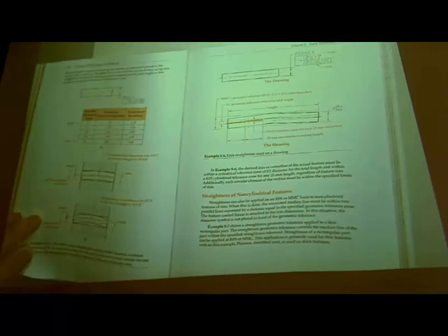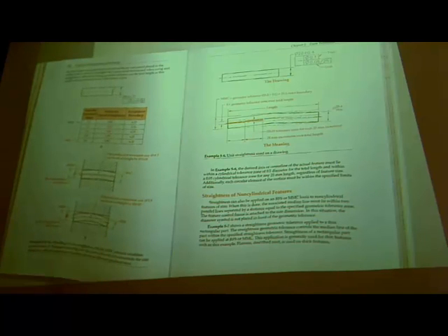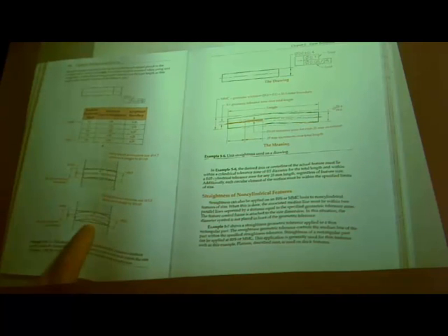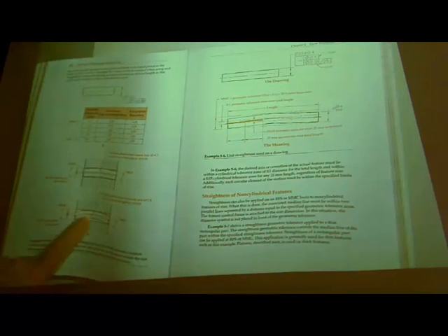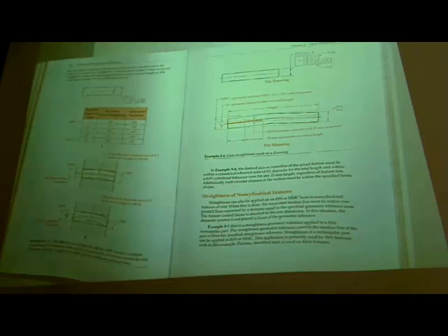Okay? So, you know, 182 shows the range of crookedness, bending, that out of straightness that you could have. And so your 6.25 is the same, but look what kind of shape it can be in. It's pretty crazy.